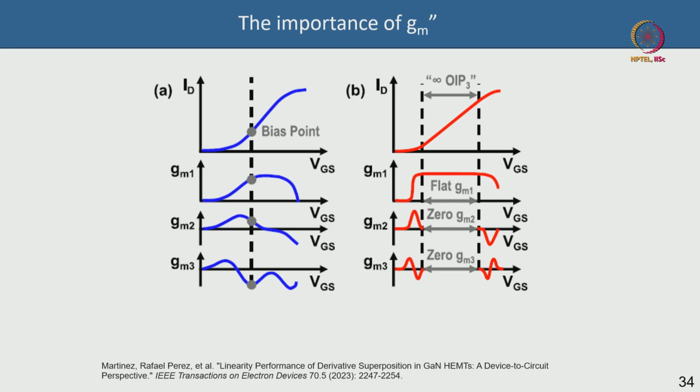So that is a very complicated linking, by the way, and this paper is mostly simulation, but that is very useful. People are yet to show experimentally many of these things, but what this paper concludes, I will come to this picture in a while, is that an excellent linearity figure of merit at the device level, such as OIP3, gain compression, IIP3, etc., does not necessarily translate to improving the peak linearity performance at the system level.